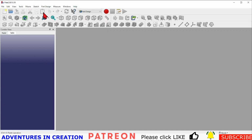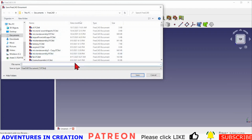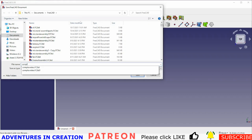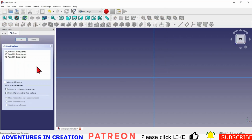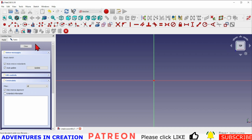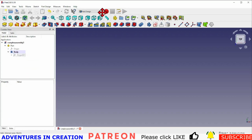Now the first thing I'm going to do is use my startup macro. And again, all my startup macro does is create a file. I'm going to call this complex assembly 3. And it allows me then to create a sketch. Now I don't actually want a sketch, so I will just finish it, close it, go back to my model tree, and delete that sketch because I don't need it. So what we're going to do is go into the assembly 4 workbench.